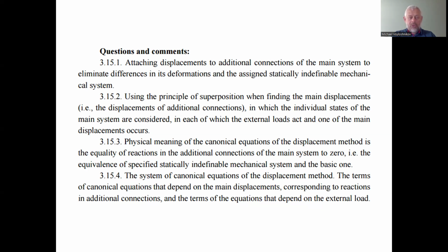So we consider the superposition. Superposition, that is all forces in the mechanical systems, assumed elastic mechanical systems, act independently, and we can find the resultant as a total of the independent action of all factors of external forces or internal forces of the mechanical system.